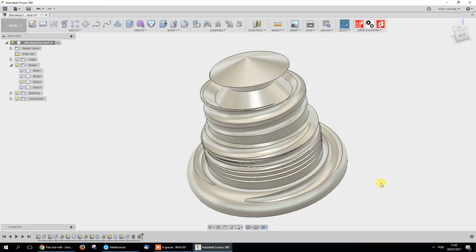It's not actually. You can create a new piece or new body without using the previous one if you want. But in that case, you need to use the initial plane, the origin, or create a new plane from others and create the coil. I just want you to practice and see how to create a coil. It doesn't need to be over the other.